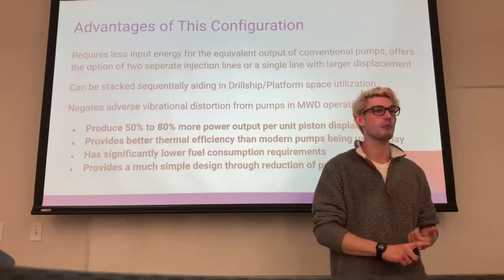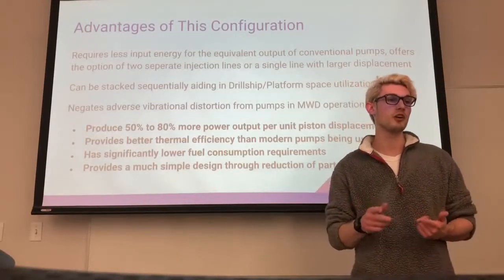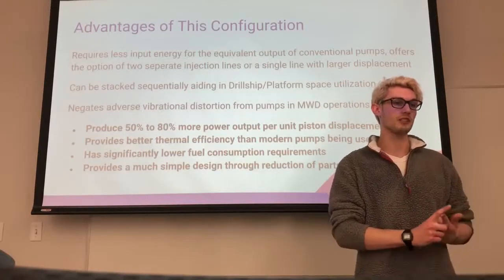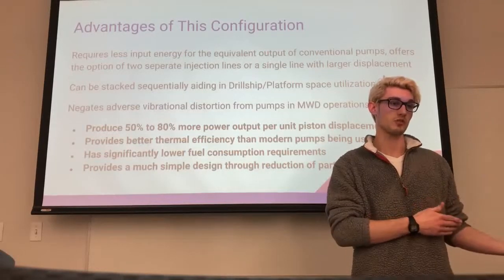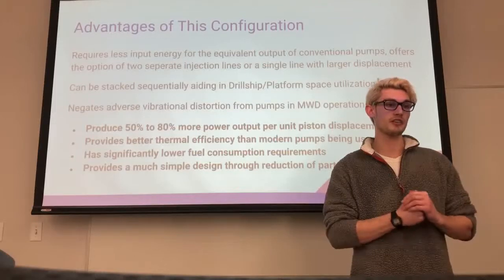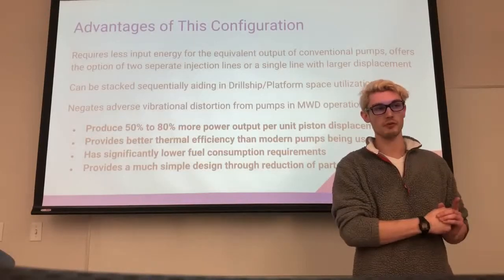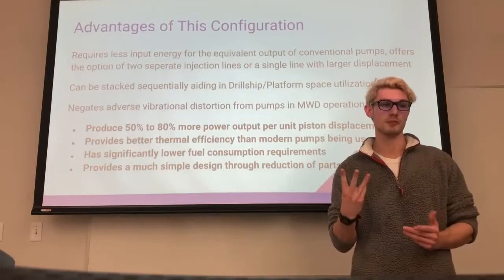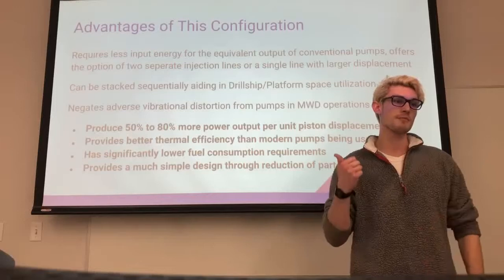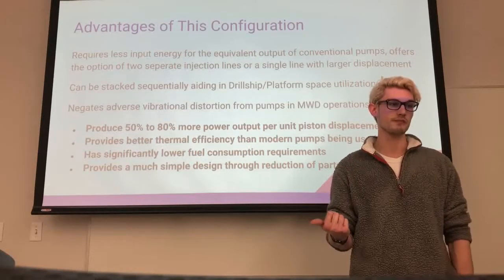Actually, based off a test run by SPE International versus the opposed piston motor and the triplex motor, which is commonly used as a pump today in most oil industries, they compared the 2 motors, and based off the results, the opposed piston engine proved to have a much better thermal efficiency based on 3 major aspects: reduced heat transfer, increased ratio of specific heats, and decreased combustion duration.